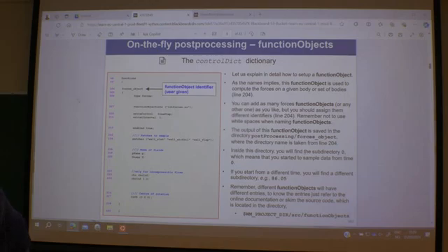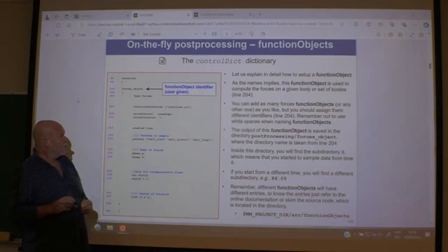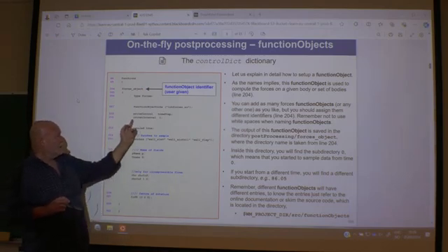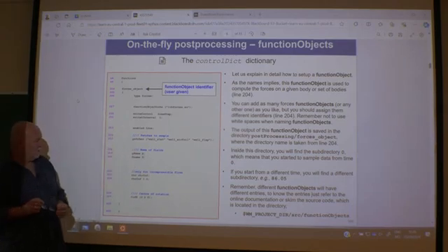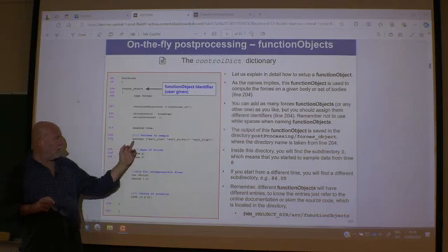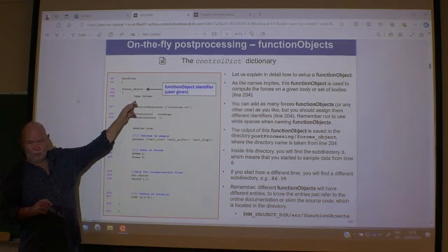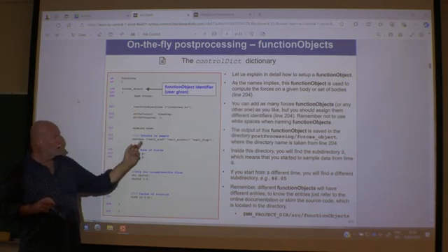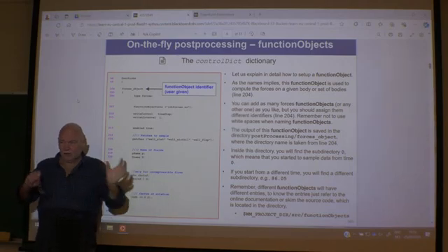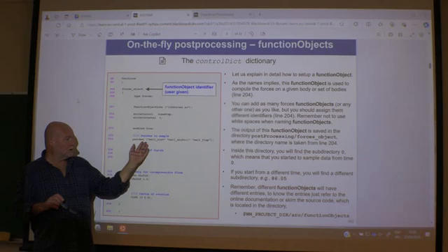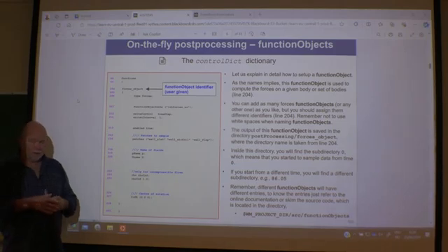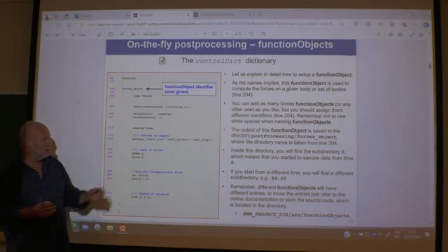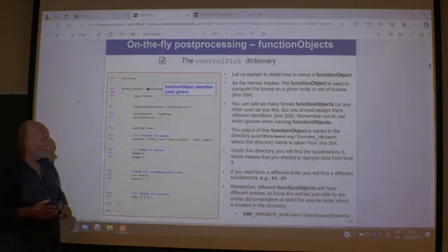Let's see what they have here. Here we have a nice one. It's a type forces. And then, yeah, we write it at every single time step. Why not? Enabled, meaning yes, it's operative. And then what patches to look at? He will report forces in Newton on the different walls that you have. If you have several different types of walls, then he can display the forces acting on these different walls. If you had more than one object, for instance, or you want to look at the force on part of an object, you just specify the different walls here, the different patches.